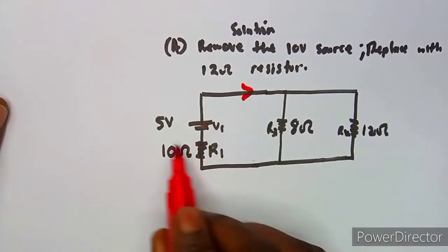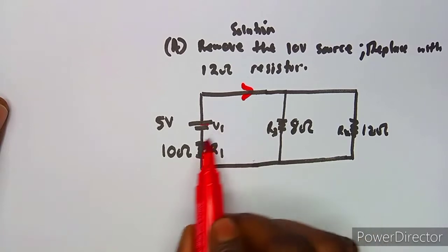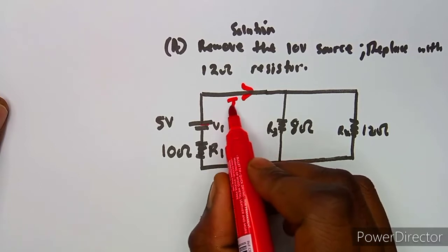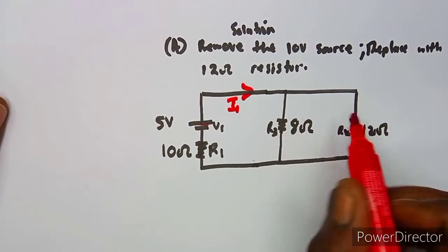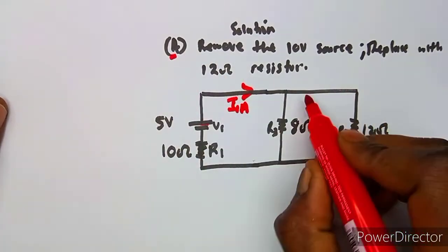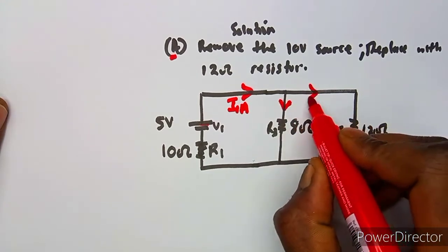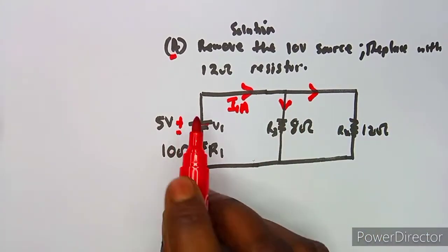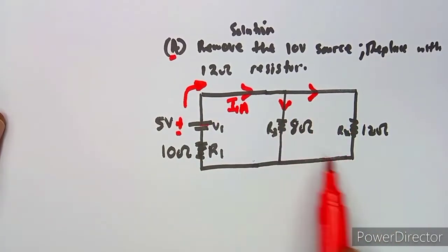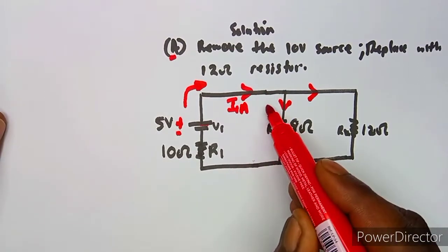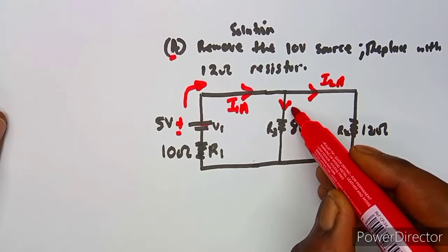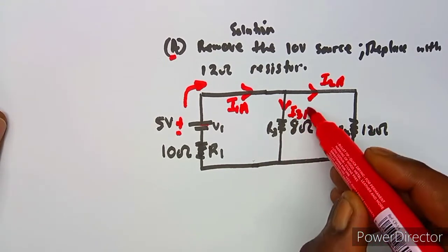So here we shall have the total current of the source, which you can write as I1, or just IT, for this first condition A. It's going to branch here. Take note, this is your positive, negative, so the current flows this way. It branches to give us I2 from resistor 2 and I3 from resistor 3, like this.